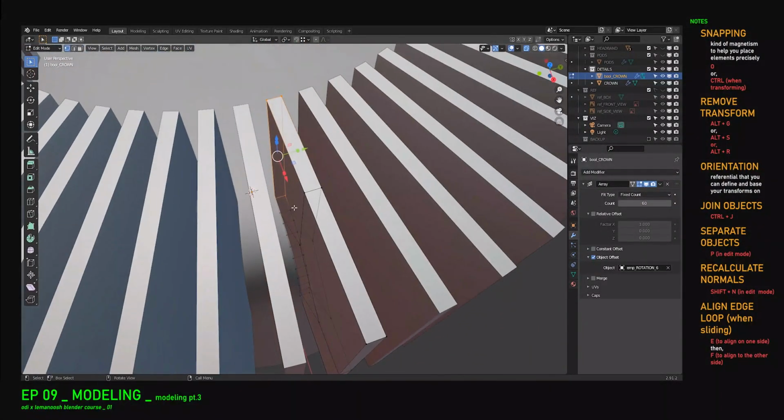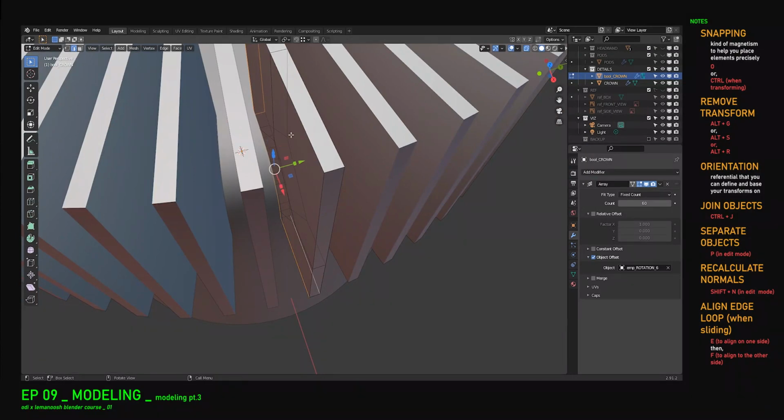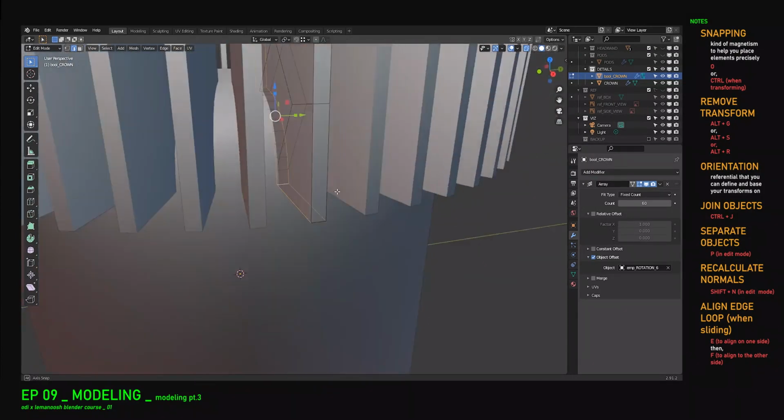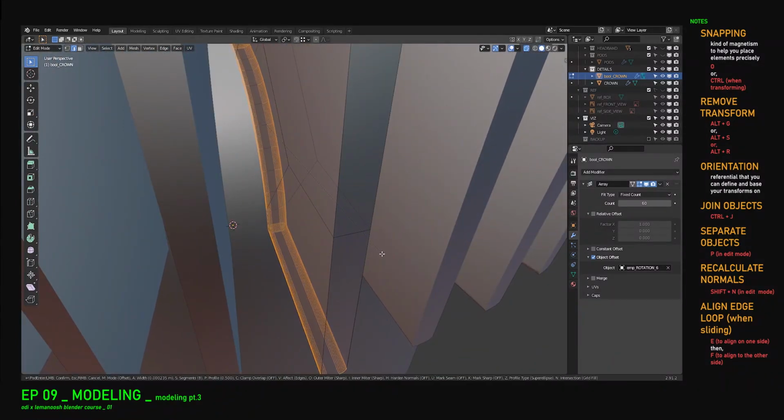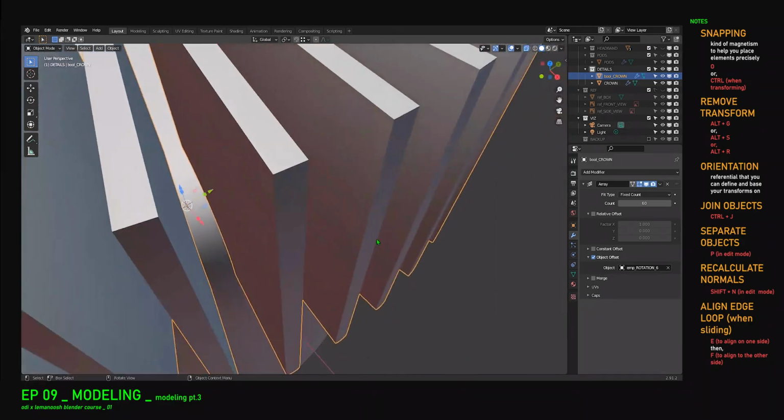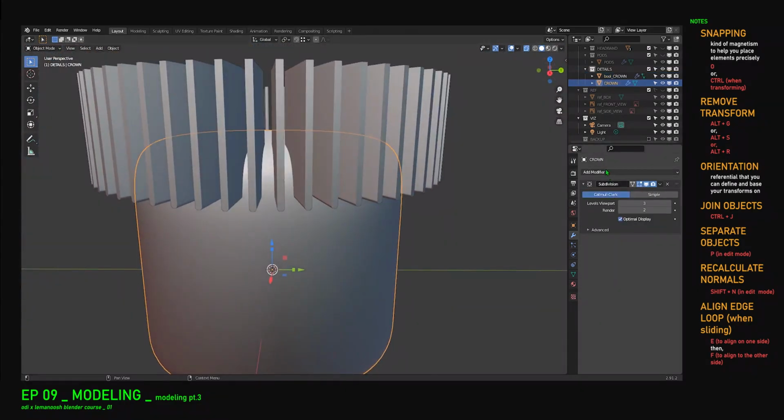What we have to do first, before we actually see what the boolean gives us, is to do some bevel here. So let's select all of these edges that we want to bevel, and let's round them off. Control B. We just want them to meet but not to intersect. Up. Perfect. So let's try that. Let's remove some divisions so that it will be easier for the boolean to do its work, and we want bool crown.